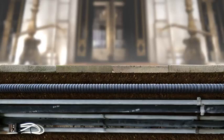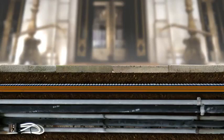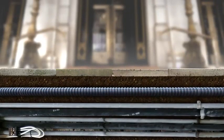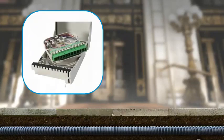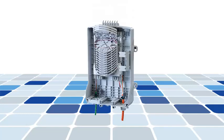If empty conduits or ducts are available, fiber optic cables can be blown into them over several hundred meters. Depending on priorities, a network operator can decide to use a connectorized, factory pre-terminated approach, splicing, or a combination of both. Connectors and optical splitter solutions guarantee faster provisioning and network upgrades. Splicing is used, for example, if a connection is difficult to reach or if a lack of space prevents the use of a cabinet with a cross-connect function.